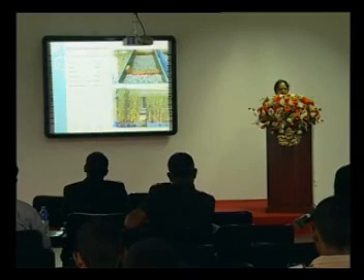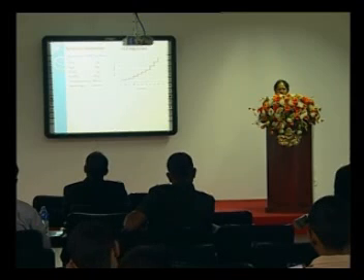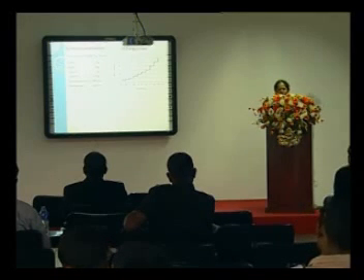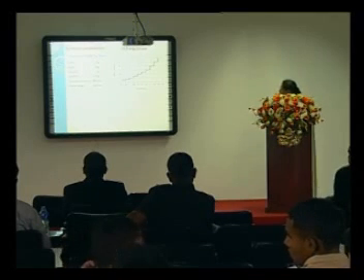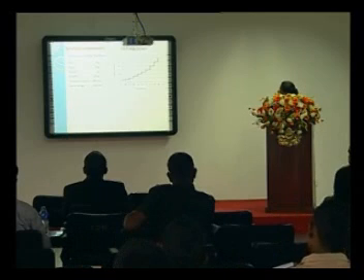and this is a full-grown wetland system. The wastewater we used here was synthetic wastewater. We dissolved all these things in tap water and prepared the synthetic wastewater, and then applied it to the wetland units. We varied the hydraulic loading rate according to the sequence shown here.